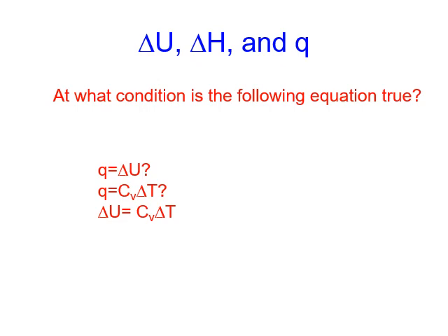So you can always calculate delta U by Cv delta T. Okay, next, when does heat equal delta H? We showed that under constant pressure, heat equals delta H. When can you calculate heat by Cp delta T? Well, Cp is the heat capacity under constant pressure. So this Cp delta T equals Q only at constant pressure. So both of them are constant pressure.